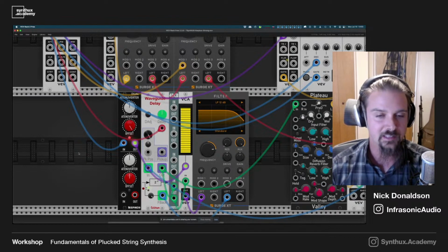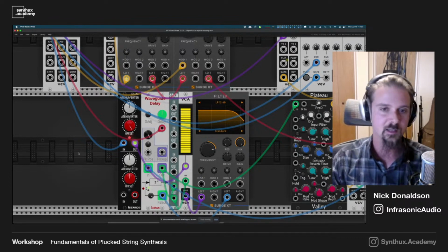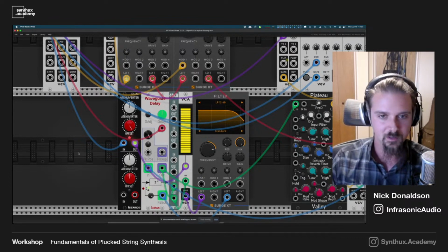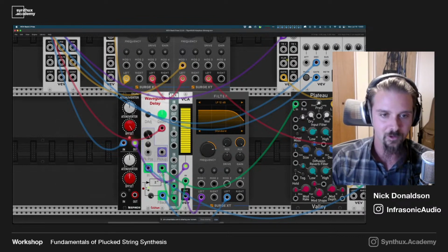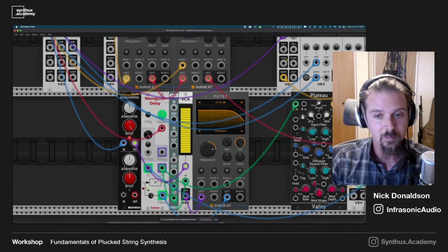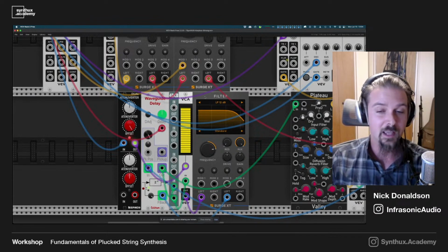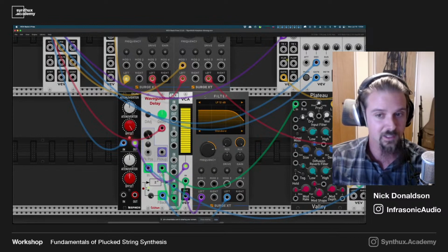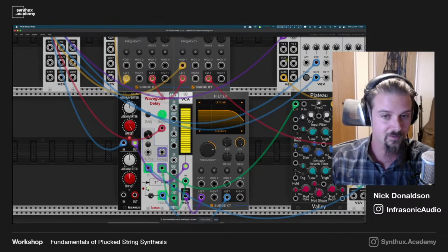So it has a constant delay of like a half a sample, because we're sort of interpolating between the previous and the current sample in that filter. So the overall group delay of that filter is half a sample, and that's what we're accommodating for when we use that filter. If we use a different type of filter, it may have a completely different phase response characteristic. It may have different overall group delay, and it may have nonlinear phase response in general, which means that different frequencies will be delayed different amounts. And in some cases, we can use that to our advantage to do crazy things to the sound. That's actually one thing Rings does.